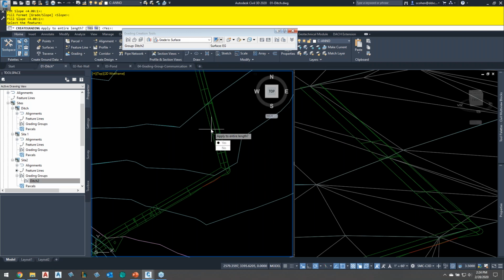And of course, you're probably saying, Seth, there's something going on here. You haven't done the proper thing yet. I'll explain that in a second. Basically, that feature line is just draped to existing ground, right? I haven't made any depth to that feature line. Well, I did that on purpose. Sometimes we forget to do stuff, right? And that's quite all right.